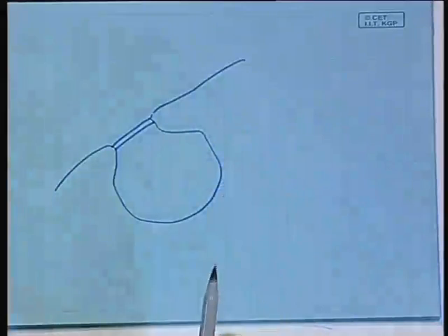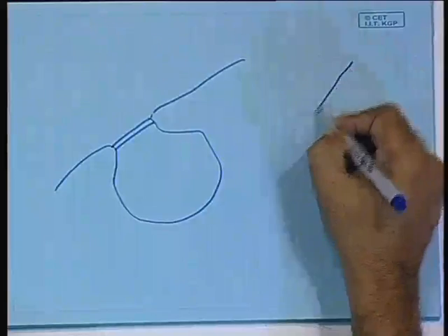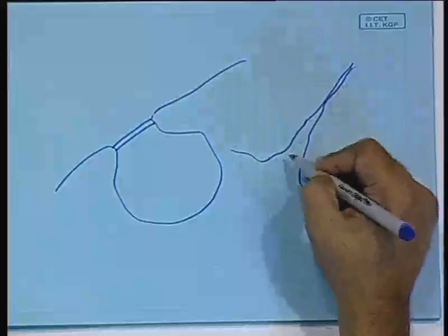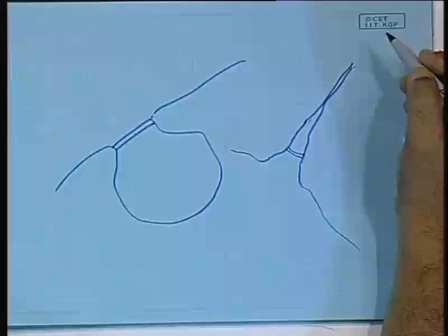That is why we have to look for the cheapest possibility, and often therefore, we have to look for this kind of specific geography of the place. Now, it happens very often in estuaries of the rivers, where, for example, a river is coming, for example, here, and it sort of expands and then it goes. So, this is the flow of the river. If you can construct a dam here, you can enclose a reasonably large amount of water mass.